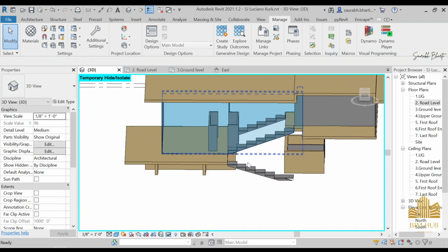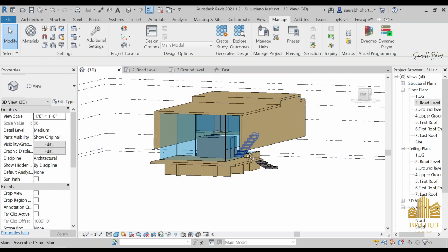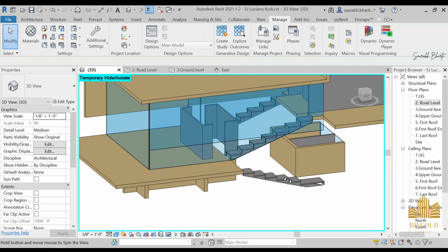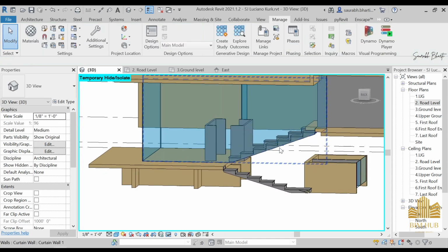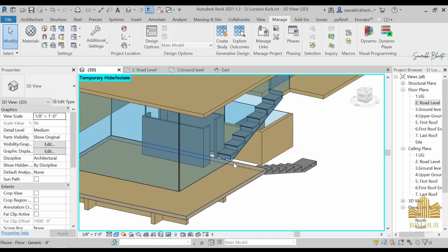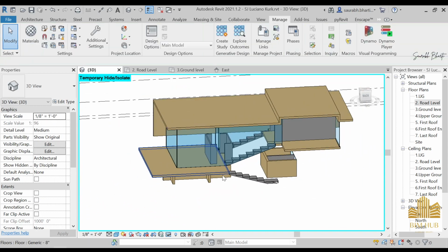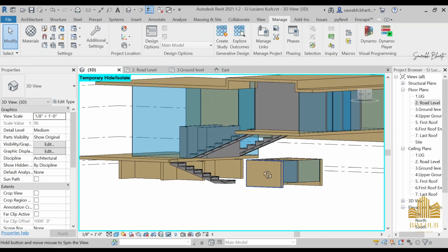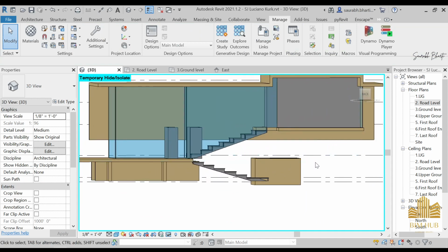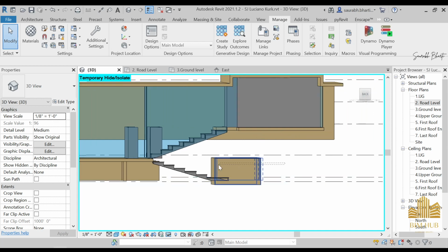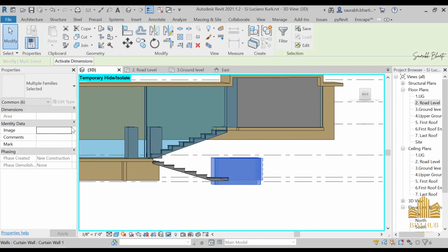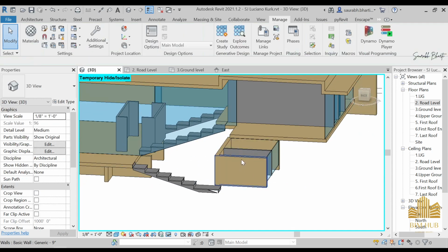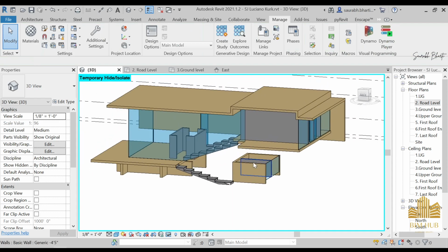Okay, this part has been done, so press HR, and everything is at the place. And let me see. Okay, there's some problem over here. I think there's an overlapping wall, so I just deleted that wall right now, and done. After that, we have made this wall, and yes, we have to attach this wall till this upper ground level. So just select all of this wall like this, and okay, not like that, just select this one of the wall, and okay, we will have to select it one by one.